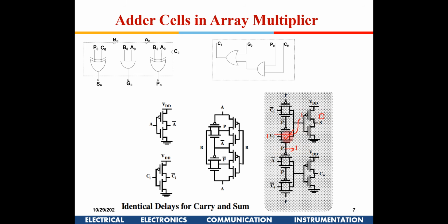The other condition for propagation to be 1 is either it is 0 1 or 1 0, since only 1 1 is not available here, right? So in that case P is 1 and C in is 0, then this is 1, 0 will come here, and it is going to be 1 here. So this is going to generate the sum. This is not an XOR gate or something, it is just a pure transmission gate. The XOR gate is used only to generate propagation and propagation bar.